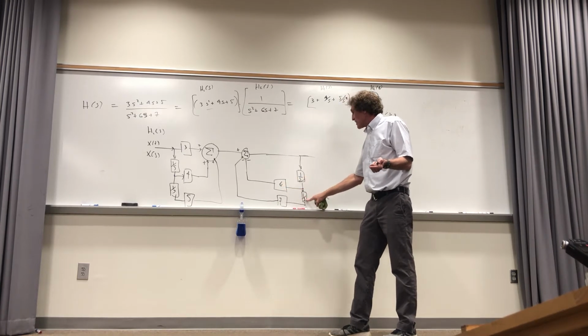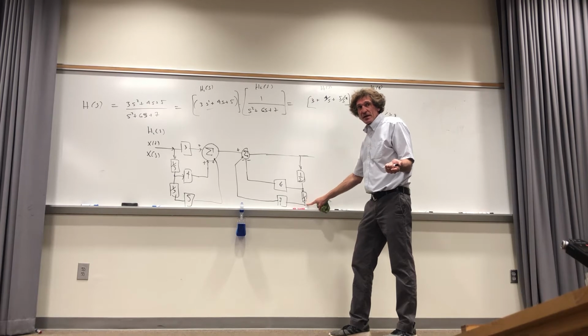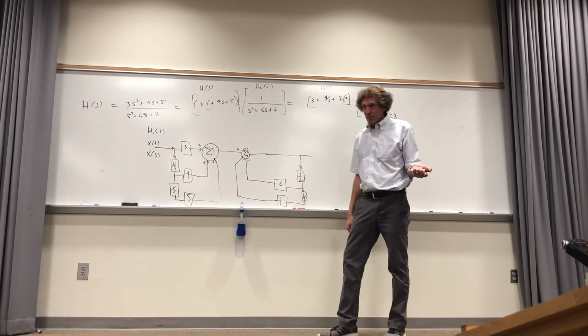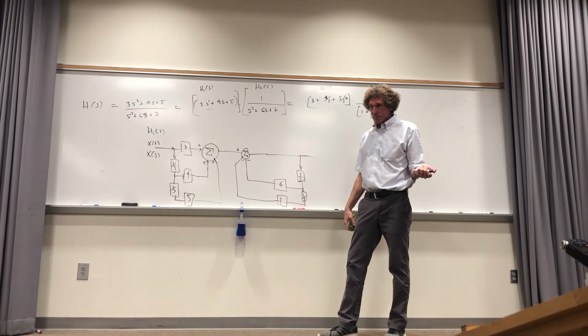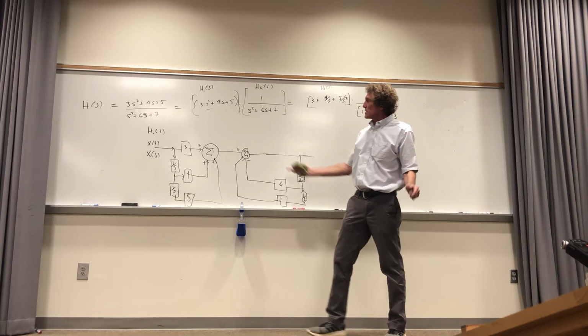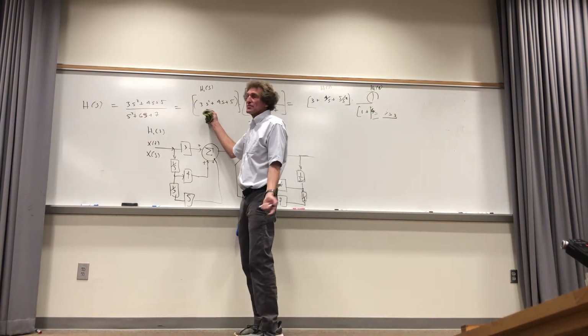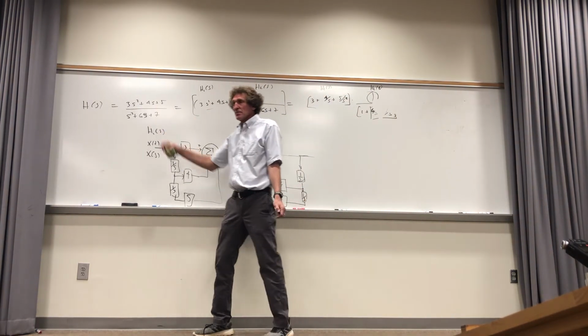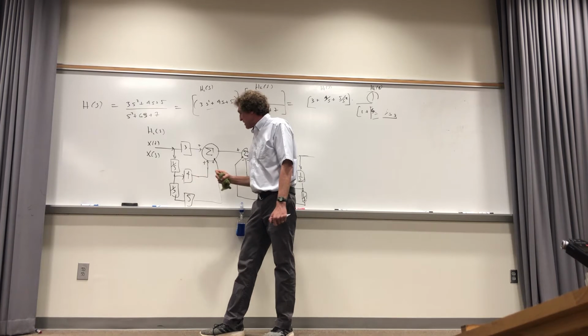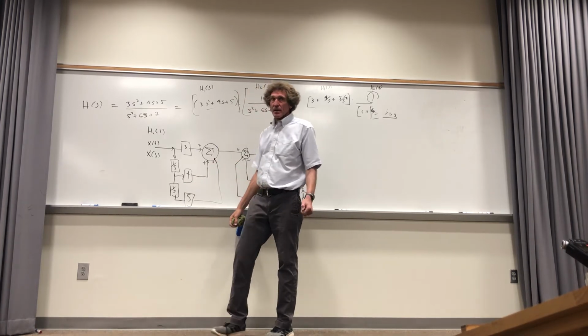And then another 1 over S is a 1 over S squared, effectively, right? So when it's coming out of here, it's 1 over S squared, and I have to multiply it by 7, but it has to be fed back in a negative way. That's the reason. Same thing on the other side, except the top is amplified by 3. Yeah, exactly. There's no negative feedback. It's just straight addition, right? You're taking the value 3 times that, then 1 over S times 4, add it, and then 1 over S times 5, add it together.